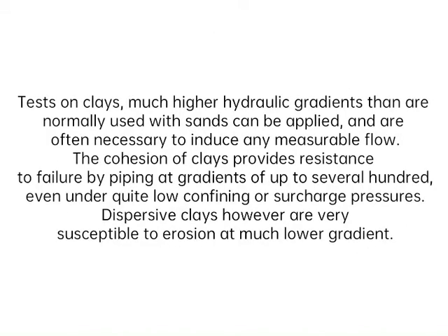In tests of clays, much higher hydraulic gradients than are normally used with sands can be applied, and are often necessary to induce any measurable flow. The cohesion of clays provides resistance to failure by piping at gradients of up to several hundred, even under quite low confining or surcharge pressures.